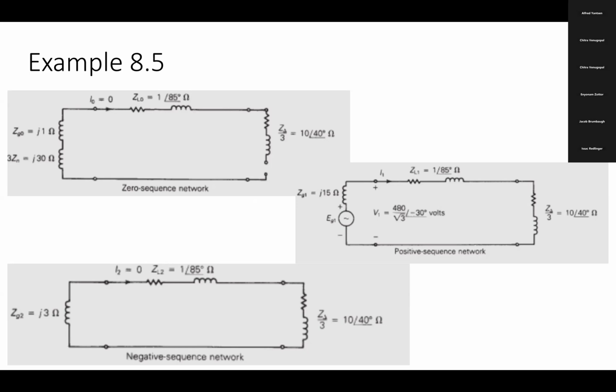Right. But just curious, because I remember reading that usually for the negative sequence, the current often sees something like a subtransient reactance for synchronous generators. Whenever I see synchronous generator example problems, they always show the positive sequence impedance being higher than the negative, even though I know the positive just depends on what type of fault analysis you're trying to do, whether it's transient or steady state.